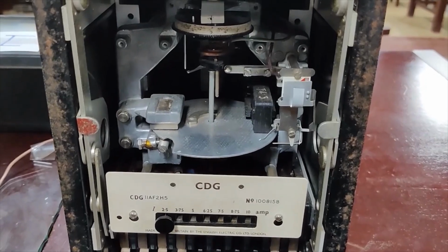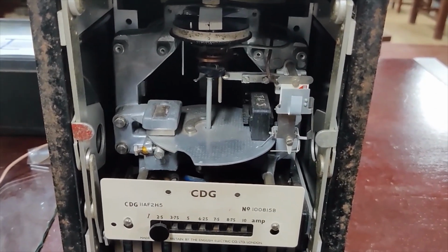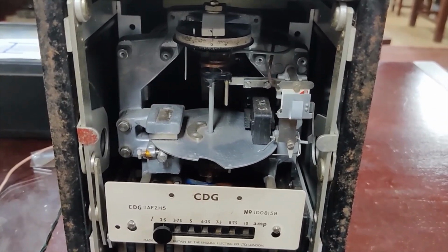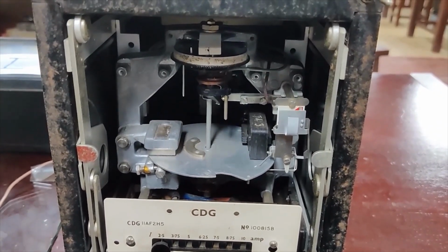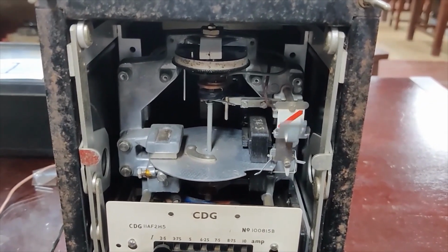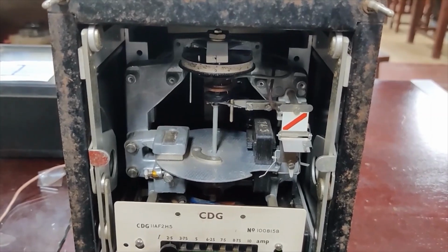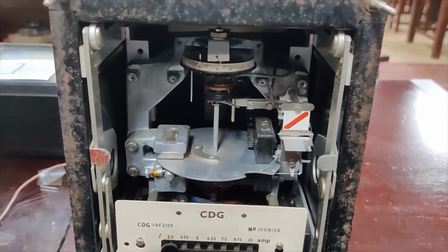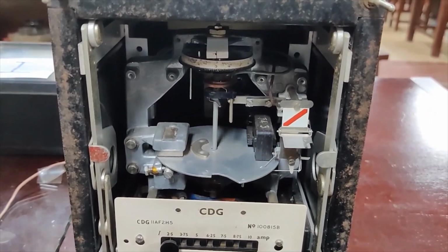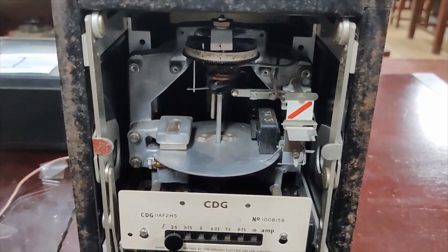Further observe the relay operation. The relay takes a certain time to operate the flag. This is the operation time for the pickup value. Wait until the flag comes back to its initial position before you operate the relay again.